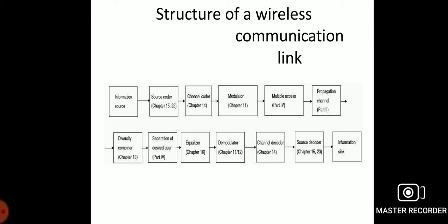Carrier recovery finds the frequency and phase of the carrier of the signal received. The soft decisions are obtained by the baseband demodulator from the digitalized data. Then the symbol timing recovery uses the demodulated information to calculate an estimation of the symbol duration.